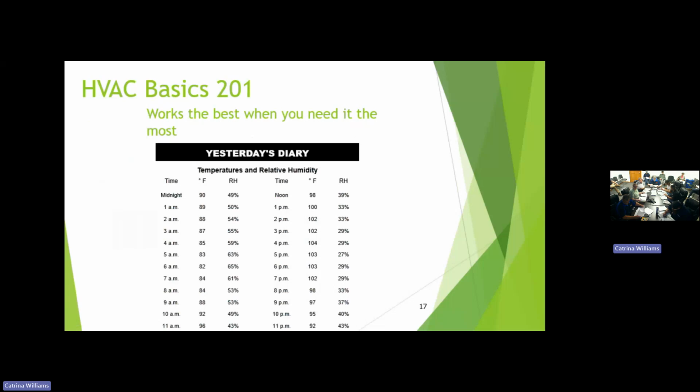You have to look at this chart here. Okay, 82 degrees on the bottom for dry bulb. Take a straight line up, we get 65% on that curve. And where is 65%?